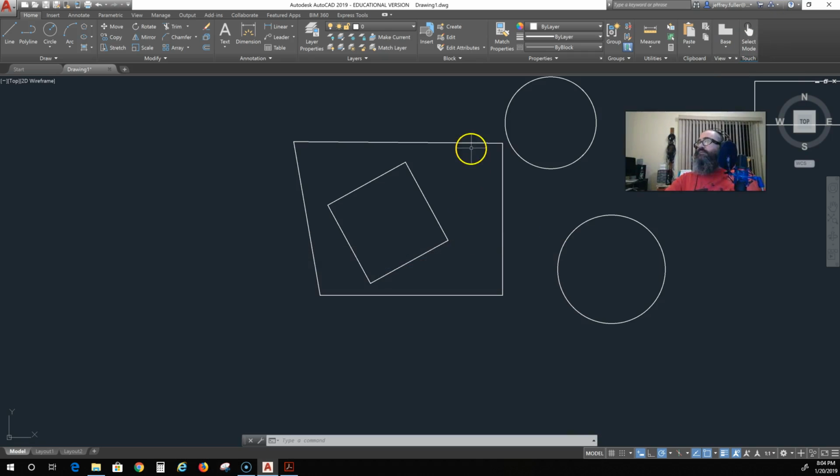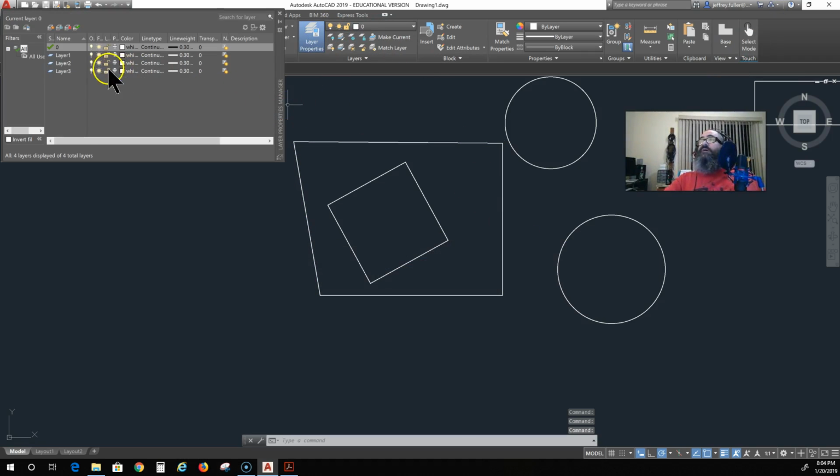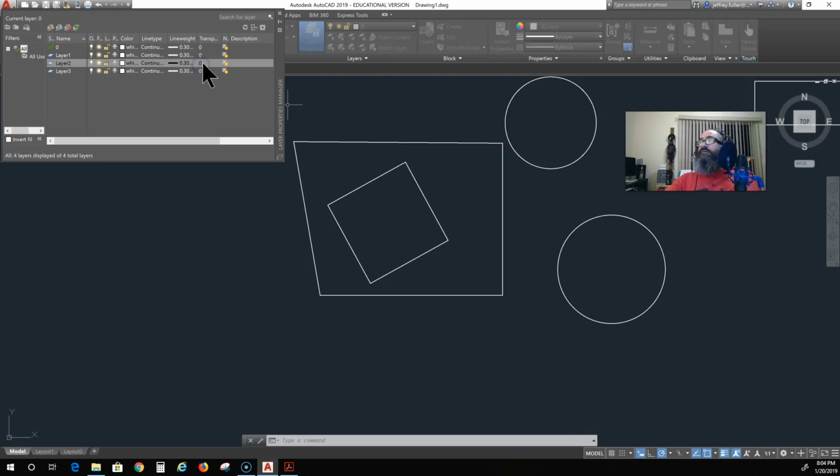And let's see, was there another way to control visibility? Let's see, line color, transparency. Okay, transparency is another way. Let's go back here to 2. Transparency value, let's just say 50, see what happens. There, it sort of dimmed out just a little bit. So right here is another area, or another place you can change the transparency.